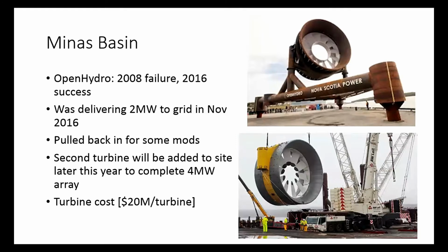The big player in the Minas Basin is Open Hydro, who has several other aliases. All these companies are constantly being bought out by each other and changing name, and it's quite hard to keep track of them. Open Hydro is a French company, and they launched this turbine here that lasted less than a week. The current was so strong that the rotor seized up, and then everything broke. So they then deployed this turbine, and you notice they took out the bit that seized up.